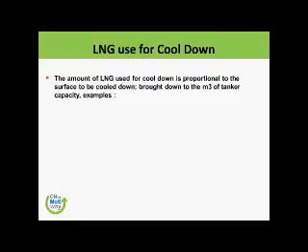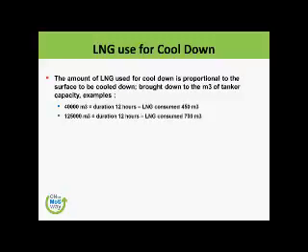So the amount of LNG used for cool down is proportional to the surface to be cooled down, brought down to cubic meter of tanker capacity. For example, we have got 40,000 cubic meters. We have got a 12-hour duration. The LNG we want to consume, or evaporate, I would say, not consume, is about 450 cubic meters.